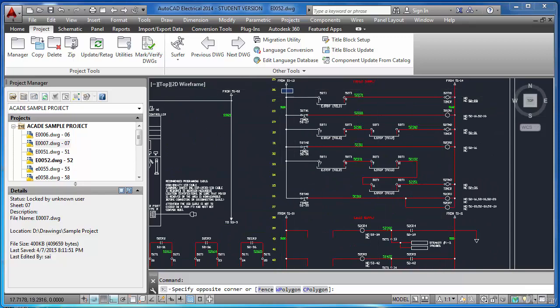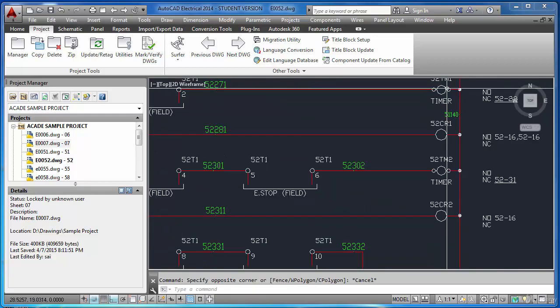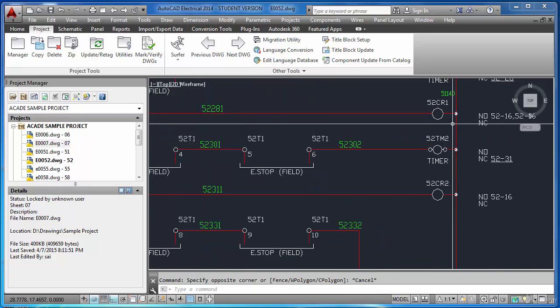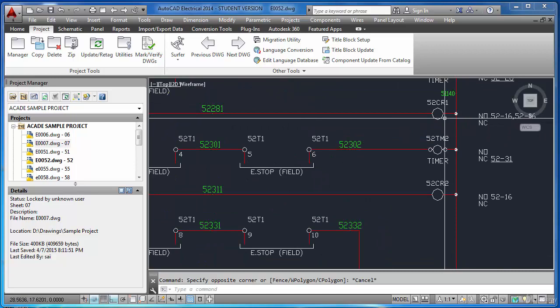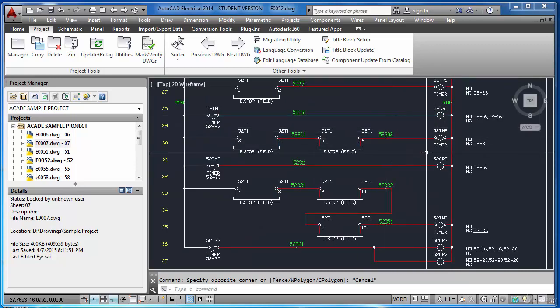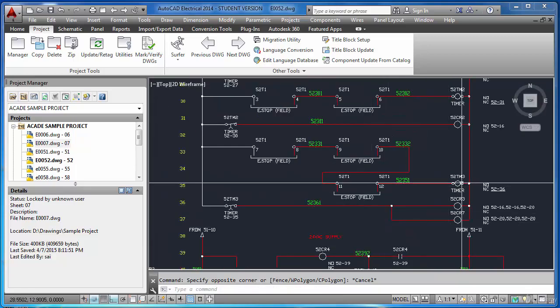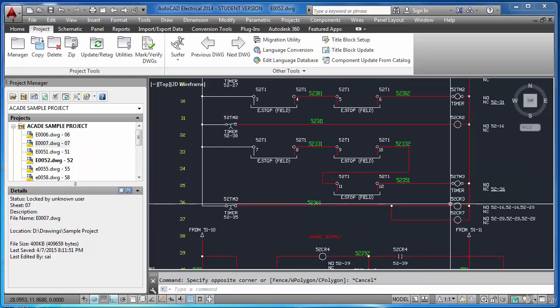This is the first set. This is through a timer. The first one is a timer. Through the first timer I am controlling the first e-stop relay, and through the second timer I am controlling the second e-stop relay. Through the third timer I am controlling 2 relays, which are here.